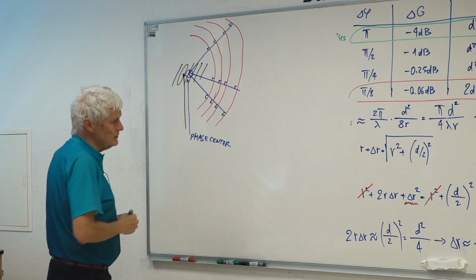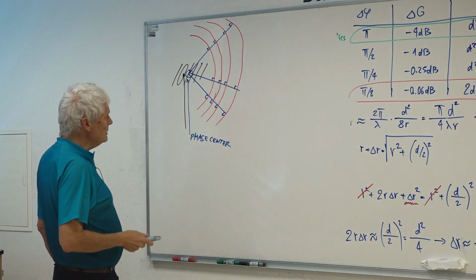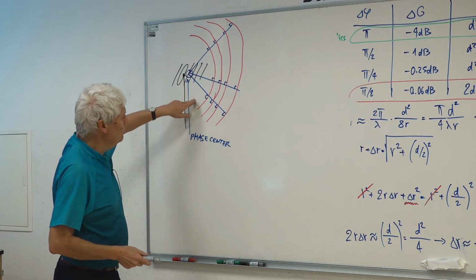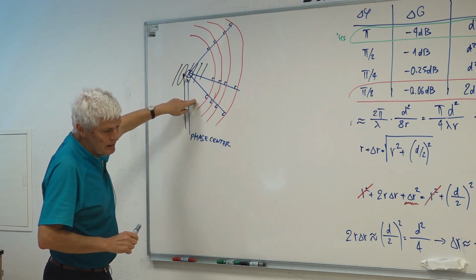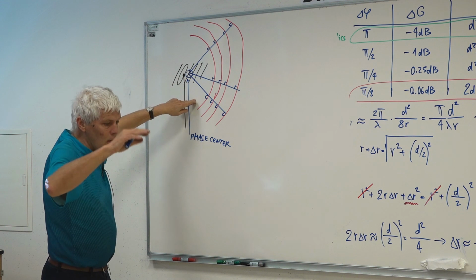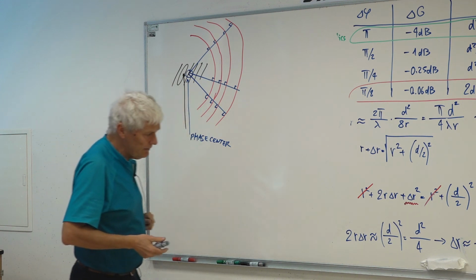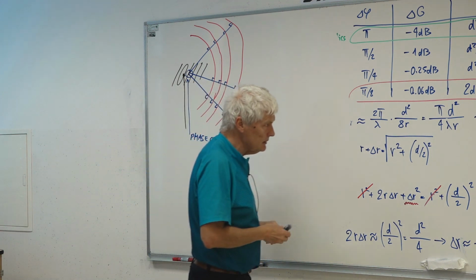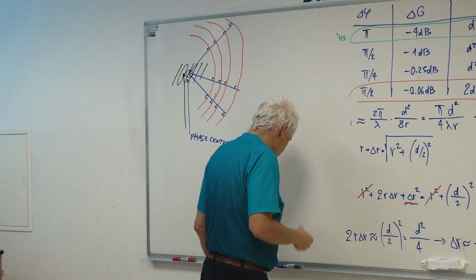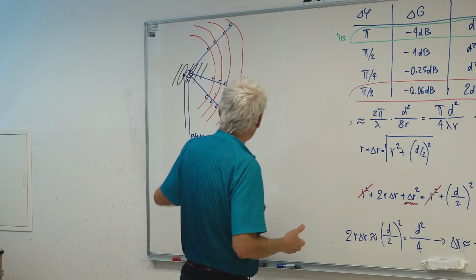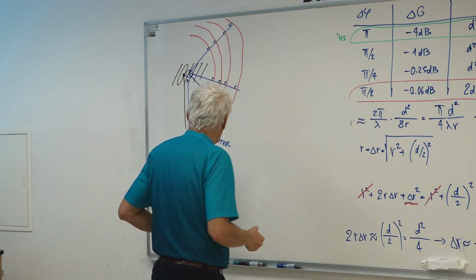If the antenna has one such point. Of course, I can only draw these lines inside the main beam of the antenna. When you go to side lobes of the antenna, usually the phase flips by 180 degrees. So it does not make sense to go to side lobes. In the main lobe, an antenna may have a phase center.